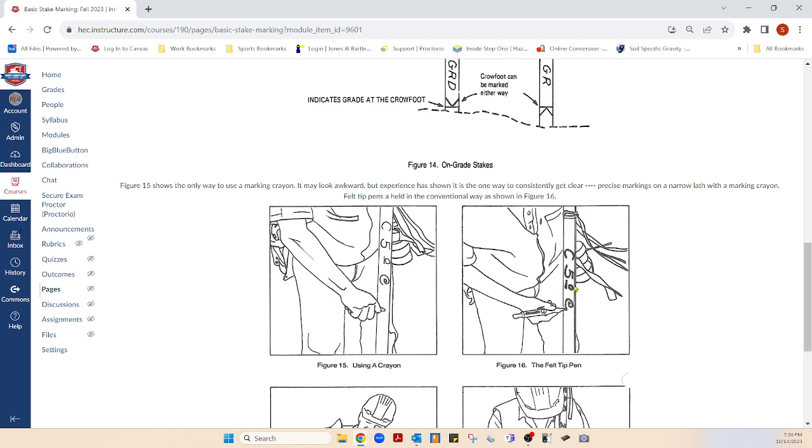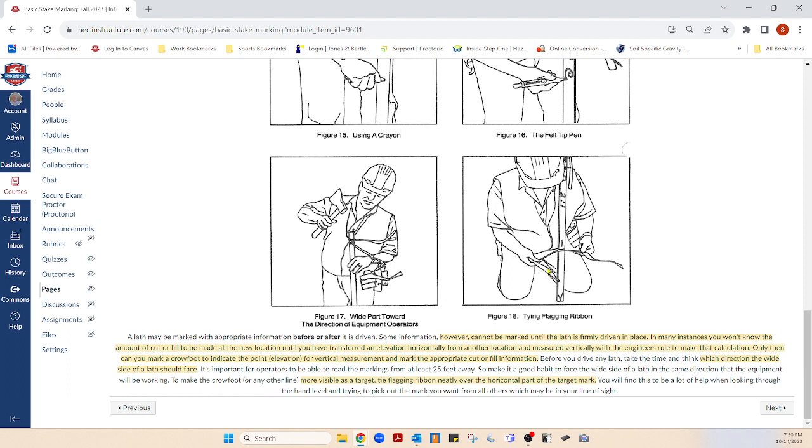That line is under that little zero, so that's 5.0. That's 5 foot even. Here, he's put a little grade boot in at 1 foot that I was talking about, and he's going to tie a ribbon around it because if he used his hand level to shoot here, he'd have to lay down. I would have hiked it up 2 feet, even that way.